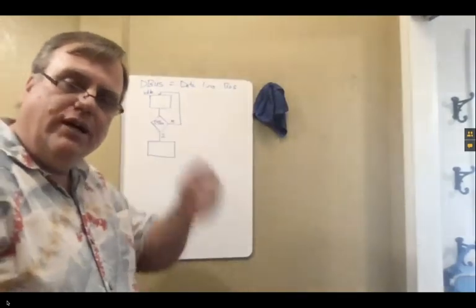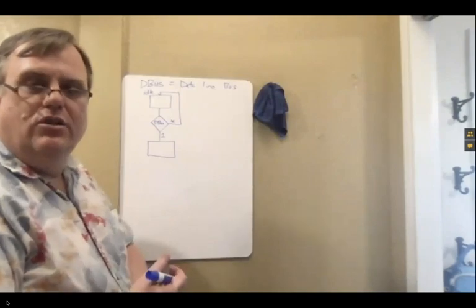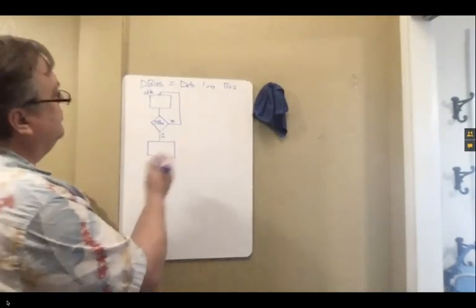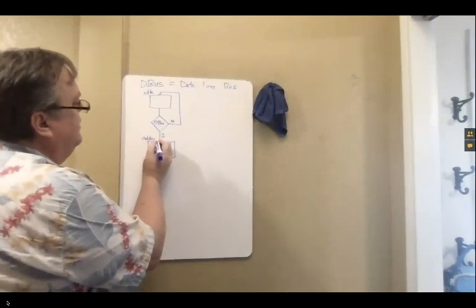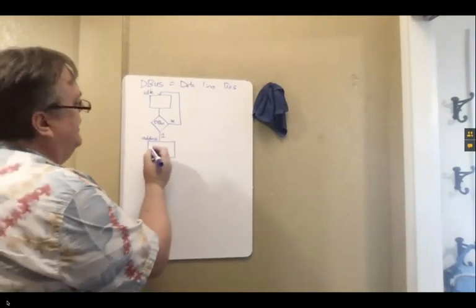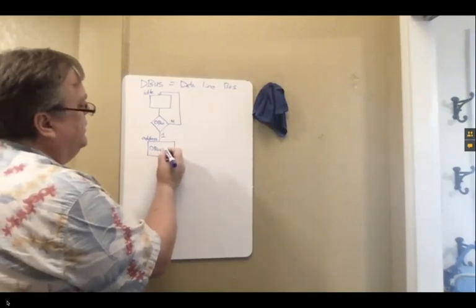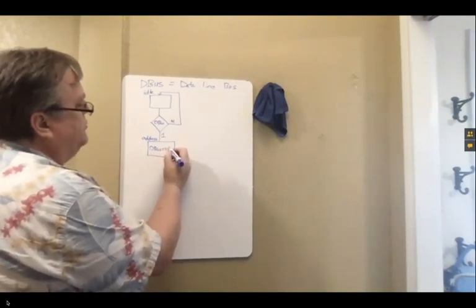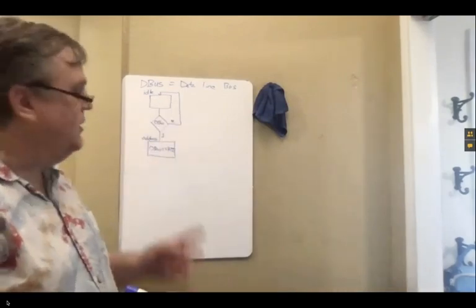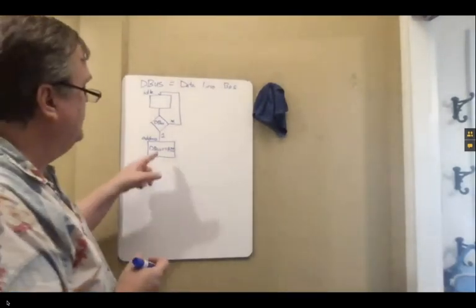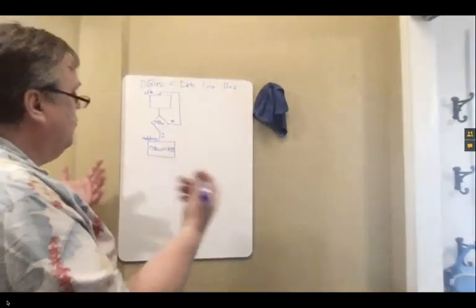And usually after it gives that initial signal to you, it'll give you information about who it is, who it's looking for. So the next state is kind of our address check. I might call that state address. And I can see whether data bus is equal to whatever my address is, which maybe I store in ADD, meaning ADD is some constant, which is my local address. And if the data bus ends up giving me my address, then I go, yay, great.